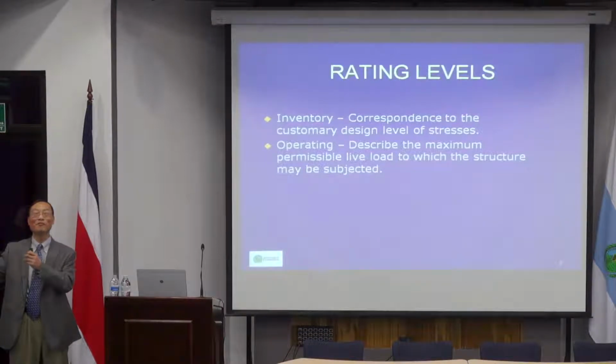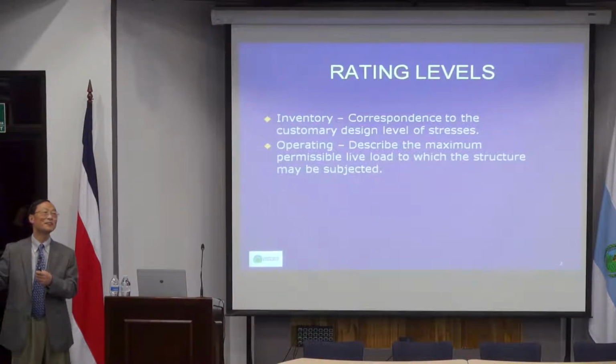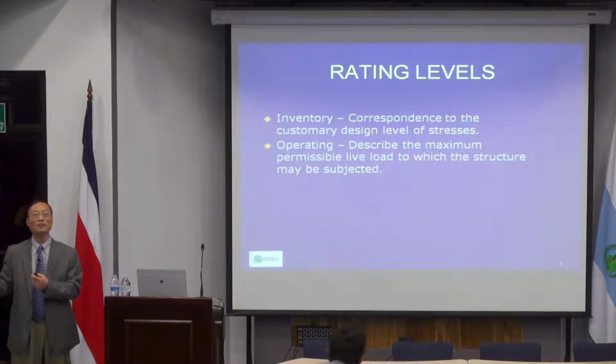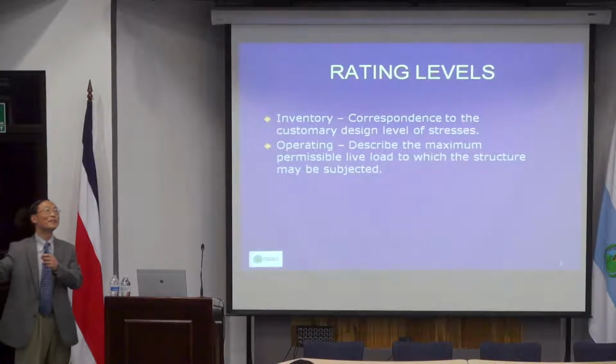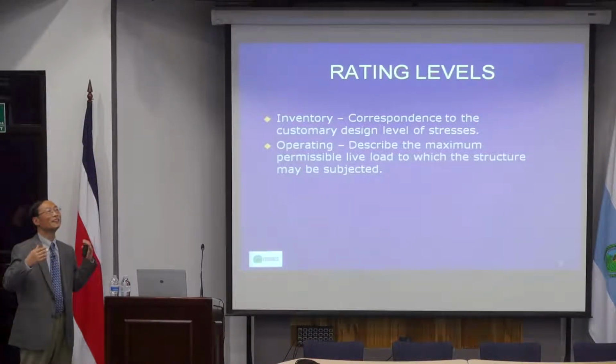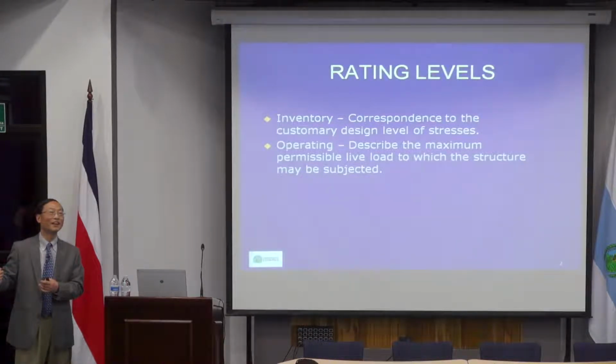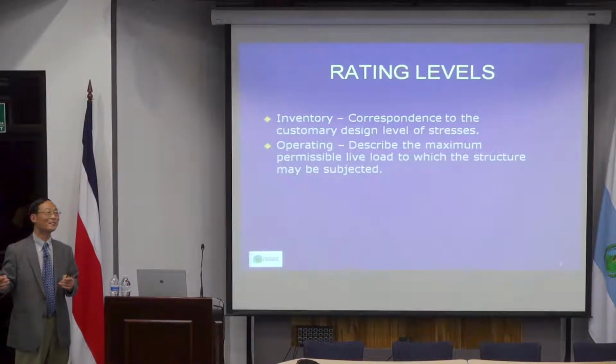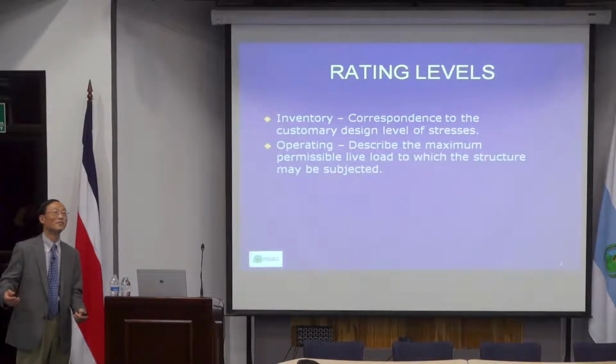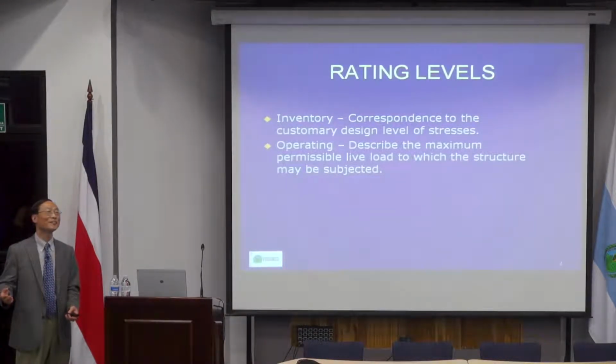each code usually gives you so-called safety factors. If you use load factor or LFD, or if you use the old method, you may use allowable stress. And that will give you basically sufficient resistance. In other words, it gives you such a small probability of failure that your structure will not likely fail. Of course, nobody can design a structure and say that I have 100% safety. It's always a probability. When the probability is so small, it will be good enough. And that is a compromise in how people decide what the load factor should be.